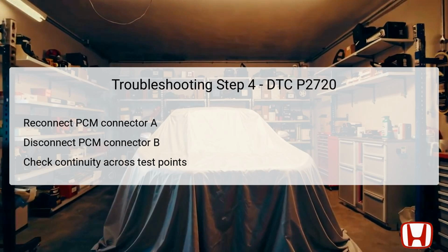A successful continuity test means the wiring is intact and functional, allowing the necessary signals to pass through. If continuity is not present, this indicates that the wiring or connectors may have faults, requiring further inspection to identify any breaks or damages within those lines.